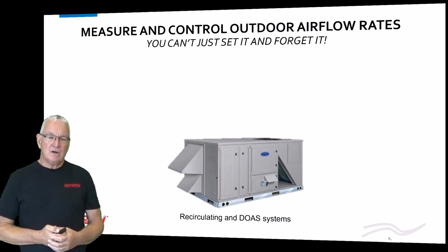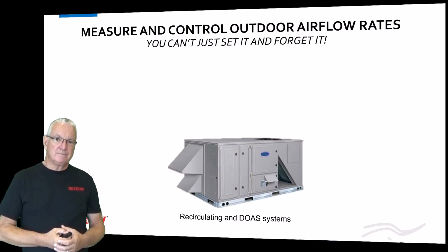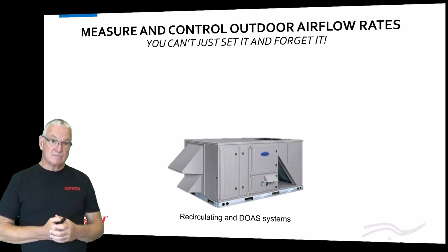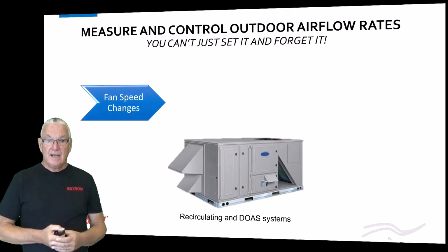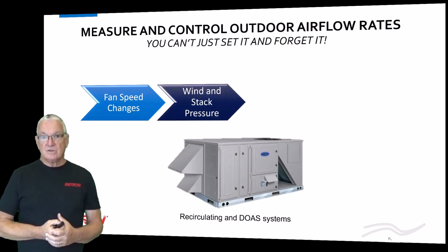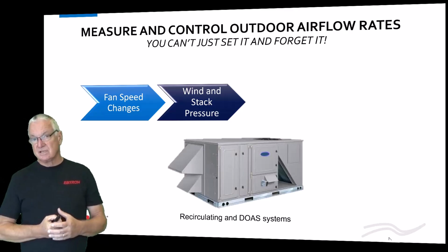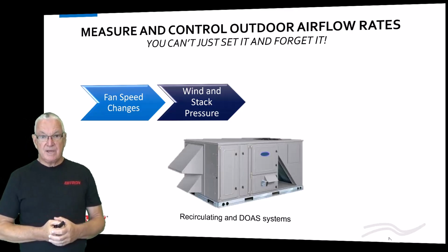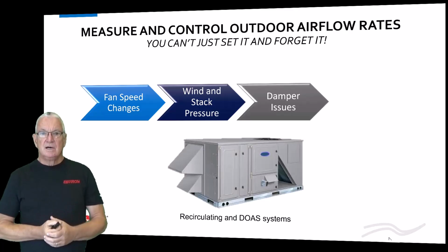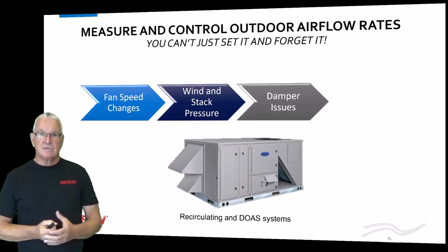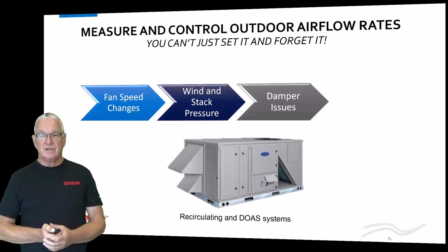And so, I'm going to show you in a subsequent presentation that you just can't set it and forget it. It's going to be because of fan speed changes and systems that have fans that change speeds. But it's also going to be wind and stack pressure on all systems, okay? Basically, that's something that seems to always get overlooked. And if we have dampers, well, you know what? We have damper issues too.